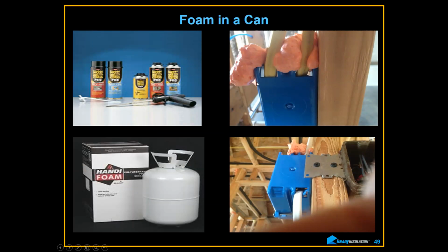So here's a great example. Squirted it from the front side, have no clue that it didn't do any good. Missed this. These have openings all the way around them. These punch outs, these all leak. They have to be sealed as well. So you see foam like this, not good. Also, what's the first thing the electrician does when he trims out? He unrolls his extended wire out there and he pulls it as hard as he can, to make sure it's tight. A lot of times you'll find this has fallen off because, again, it's rigid, it's not flexible.